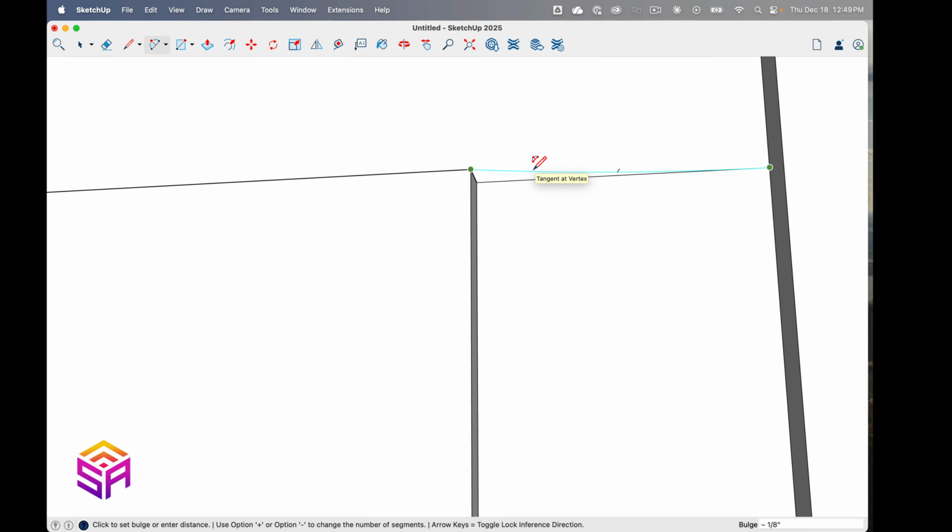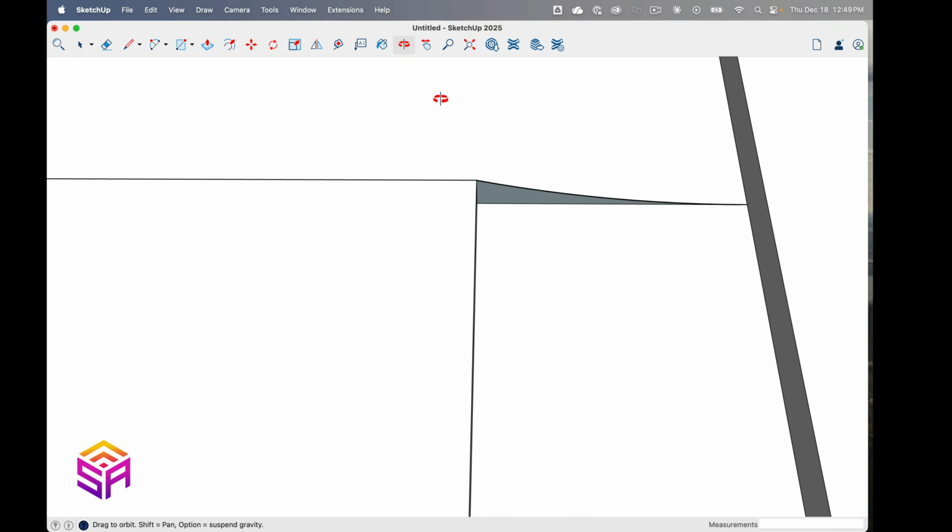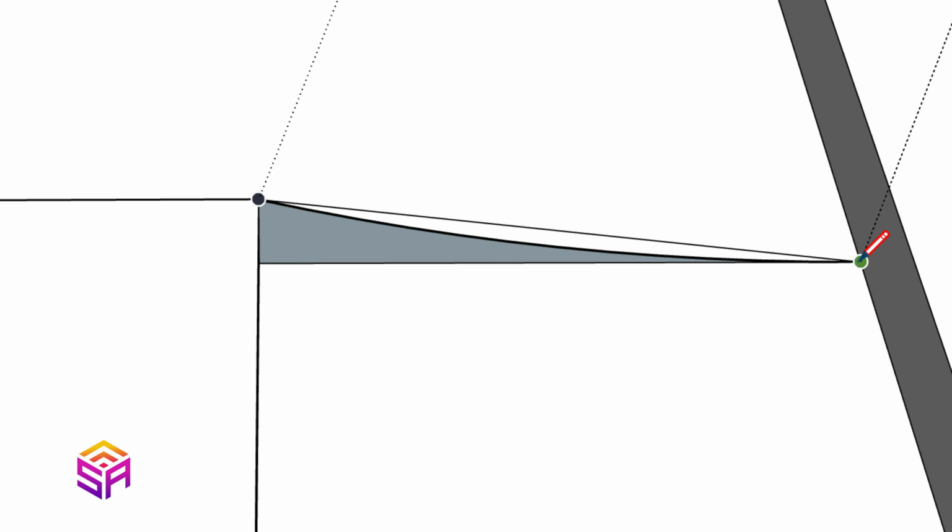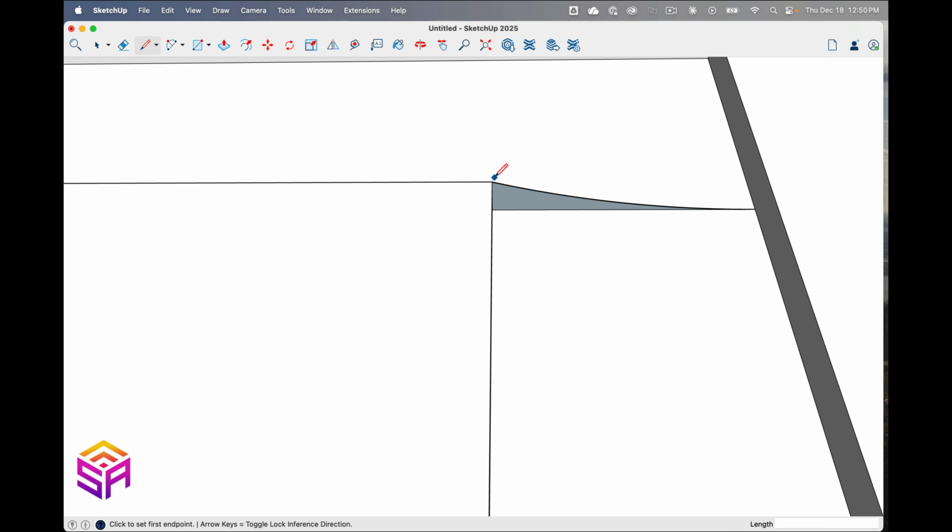And so not that it matters hugely, but I'm going to do a 1/8 here. It looks like it's pretty good. It looks like I'm not cutting below my panel. And that now is a profile that's different than just this linear profile that we created earlier. And so I'll put this in temporarily so you can see it, so you can see the difference here. Again, you could create OGs or kind of whatever design you want in here.